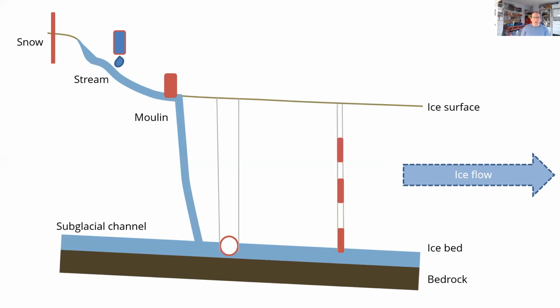And then the final group of instruments are these sausage-shaped borehole instruments, which, because I work with German-speaking researchers, became known as Cryowurst for sausage. These are intended to give more of an insight as to what's going on in the glacier dynamics. So we have one at the bed, which is measuring the subglacial conditions, and then several more further up the glacier, and they measure temperature and borehole tilt, so you can get an idea of how the glacier is moving.